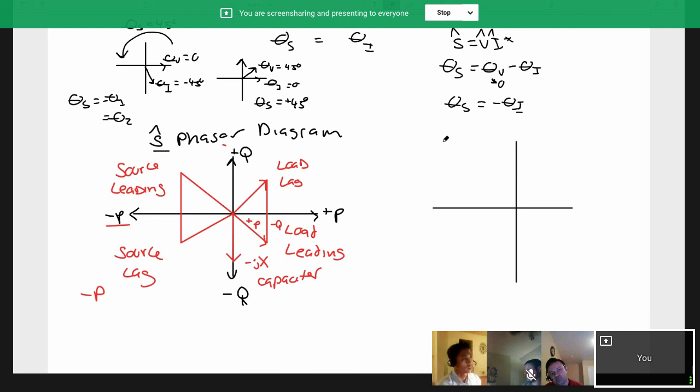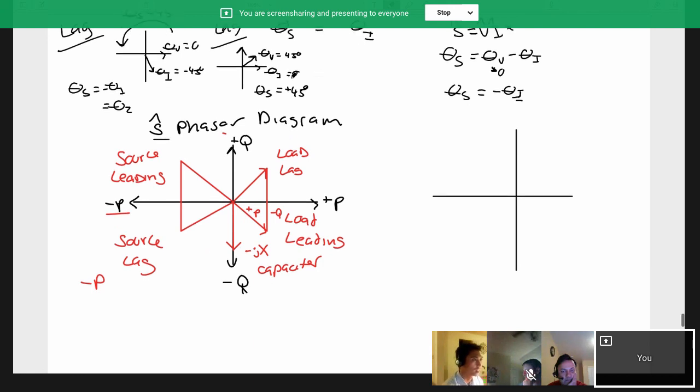Really quick, we're going to compare our phasor diagram, exactly what we did for voltage and current. Is this lagging or leading? Lagging. How can you tell? Your current is lagging, negative. How about over here? Our current is not negative. Is this lagging or leading? Lagging. How can you tell? The angle from the voltage, V and I, because I is still behind.